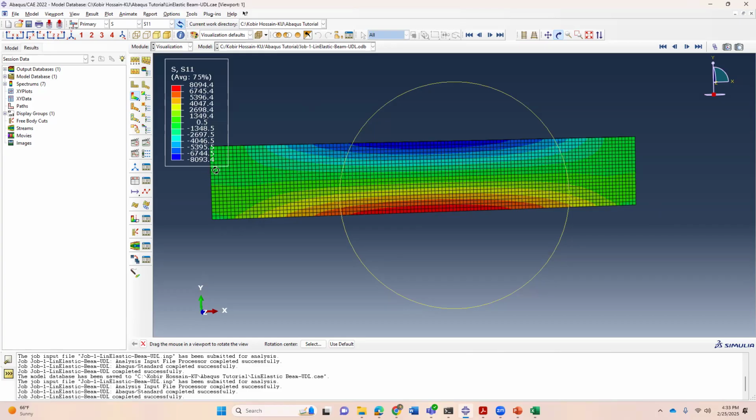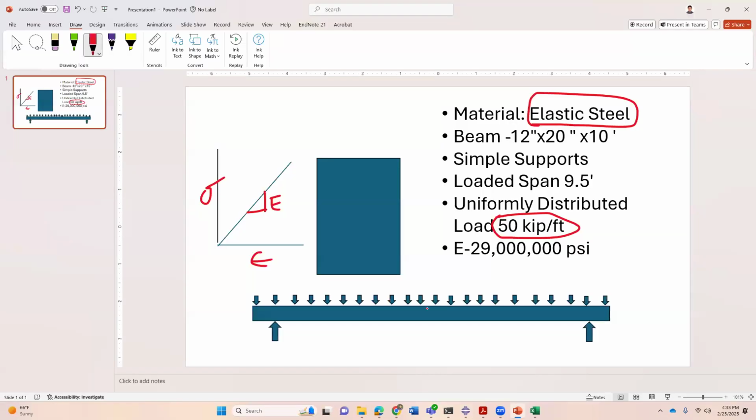So in this region, there is zero moment basically and zero flexural stress. So that's longitudinal stress, means it's flexural stress. The top is in compression, bottom in tension for a simply supported beam under uniformly distributed load over the whole area, like this one. So the maximum moment is right here, and we know the moment diagram is like this, and maximum moment is here, and the stress distribution, if I draw on this beam, the compressive stress varies linearly on